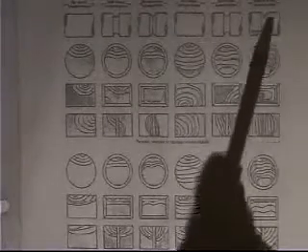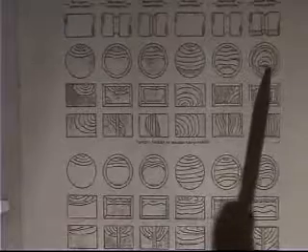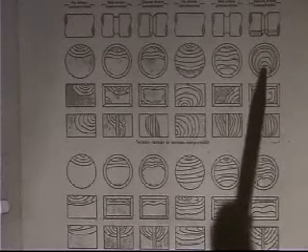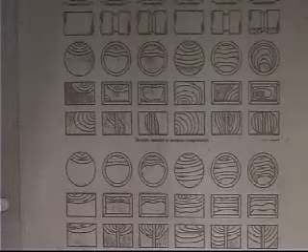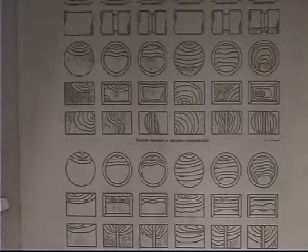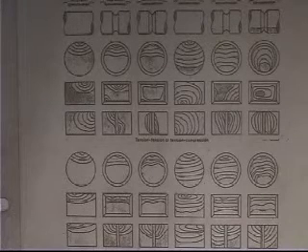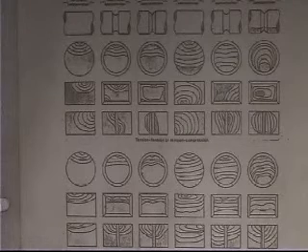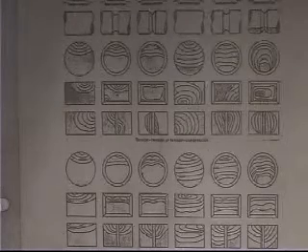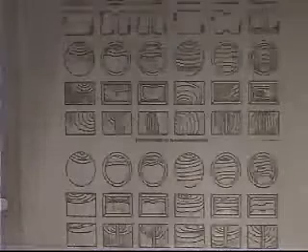And so this is actually a tensile stress, but you end up with a final fracture area that's right here. Very small final fracture area. That means the loads on this thing in normal service were very, very small. If the loads were very, very small, well, I should have been at my fatigue limit, right? In terms of the nominal stress, that's true, but I had a stress concentration which magnified them.